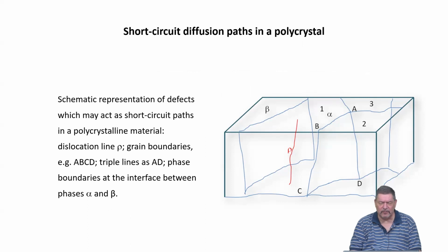We have a material, and even if we have annealed it basically to death, meaning that the material will not show any longer over reasonable time scales any time dependence, we still have grain boundaries normally. We have a polycrystalline material, we have dislocations, we have outer surface. So it means that we have always microstructural variability.